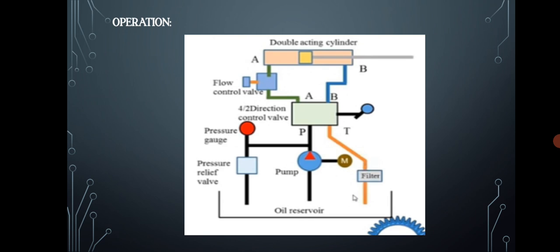The hydraulic pump draws up oil from the oil reservoir and sends it to the control valve under high pressure. From the control valve, the oil goes to the hydraulic cylinder to operate the piston, which in turn raises the lifting arm. The lifting arms are attached with implements. The hydraulic pump is operated by suitable gears connected with the engine.